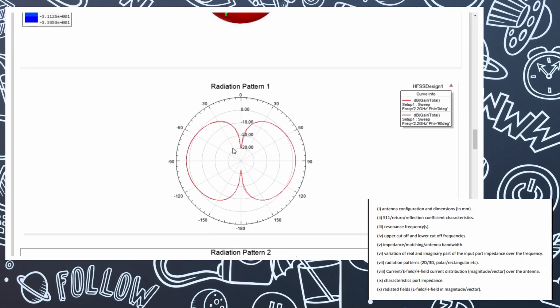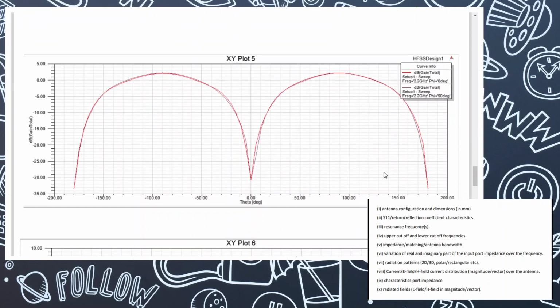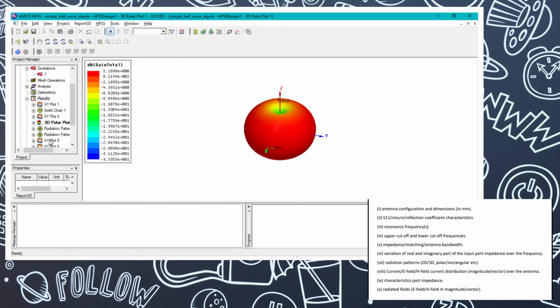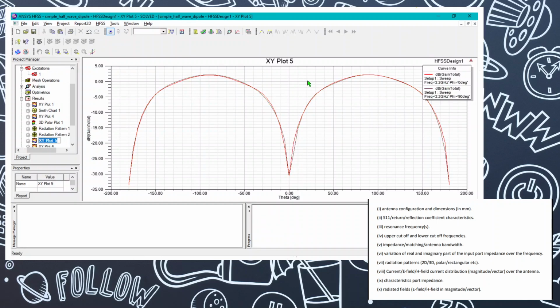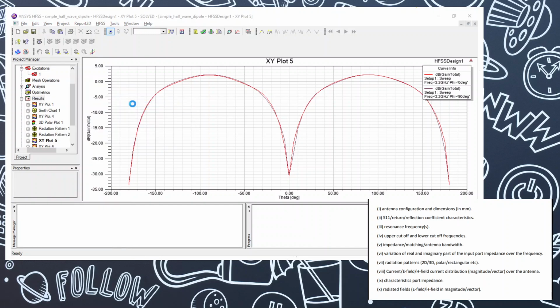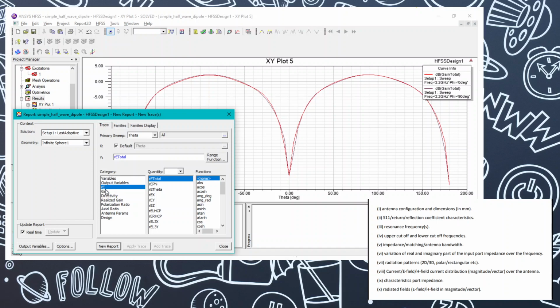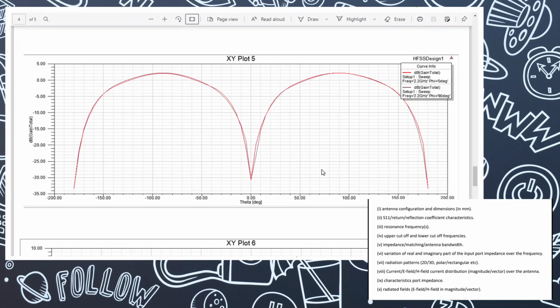The radiation pattern shown is the gain total, and the gain phi is shown in this part. After that, we are going to see the gain in rectangular form. For viewing the gain in rectangular form, we come over here, and we have the gain total in rectangular form. To view it, you can go to Far Field Report, Rectangular Plot, and just go to this gain total and click, and the dB unit should be selected for this graph. The rectangular plot will be created, and click on New Report after that.